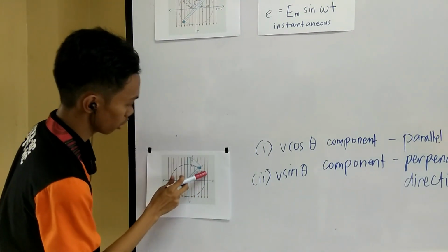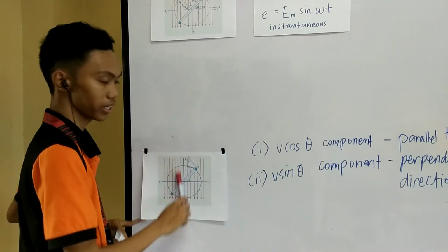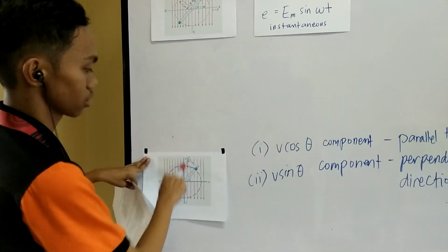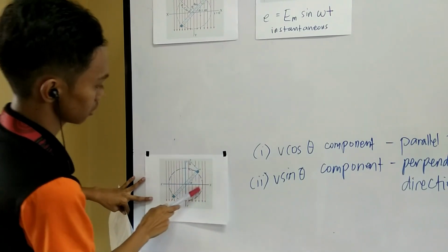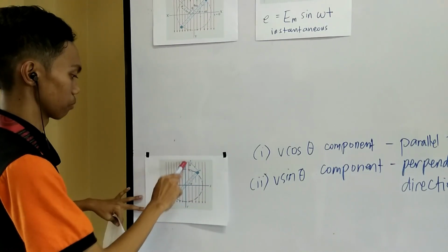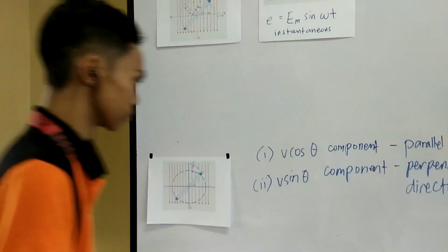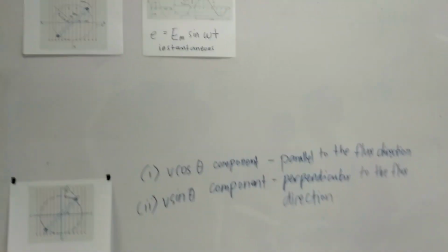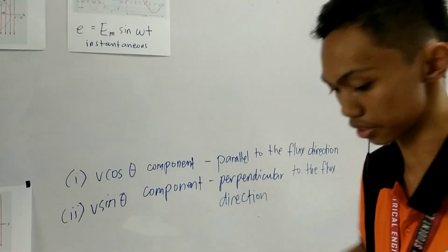Now if this coil rotates through the magnetic flux and is parallel with the y-axis, no flux is cut, meaning no EMF is generated. However, if it lies at an angle not parallel to the magnetic flux, flux is cut and EMF is generated. There are two ways of resolving its components. When the coil has turned through the angle theta, its velocity can be resolved in two ways.